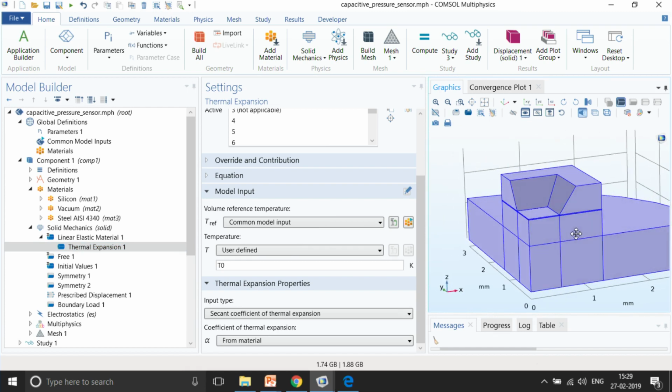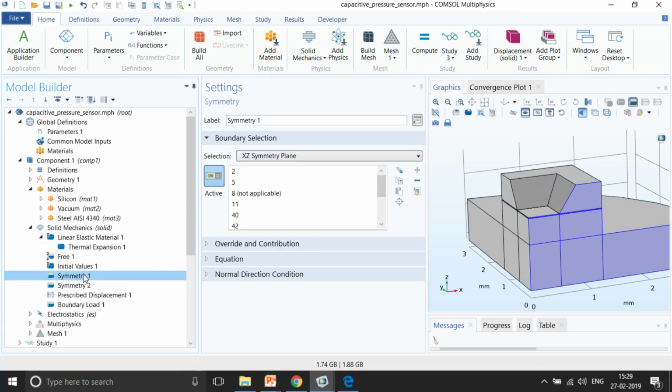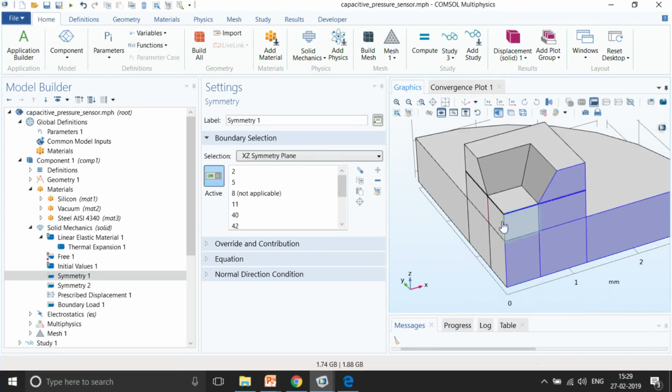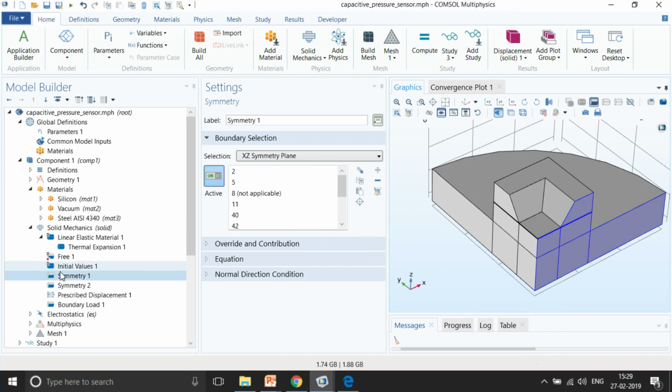So this is while the fabrication is going to take place. Because of the fabrication issues, there is also some kind of deformation that comes into the picture because of thermal expansion. We definitely want to give a symmetry boundary condition because we are modeling only a quarter part. So we have the symmetry boundary condition on the right side and on the left side, and then we give